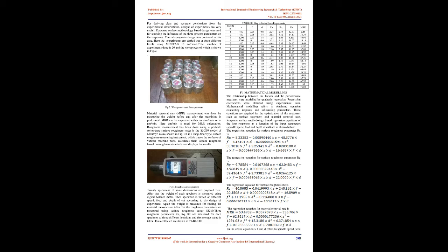The optimum cutting speed and feed obtained were 103.05 m/min and 0.9 mm/rev for roughing cut and 162.02 m/min and 0.24 mm/rev for finishing cut respectively. It was found, by comparing the obtained unit cost of $1.6262 with that obtained in genetic algorithm and simulated annealing, that ant colony algorithm performed better than the other two.